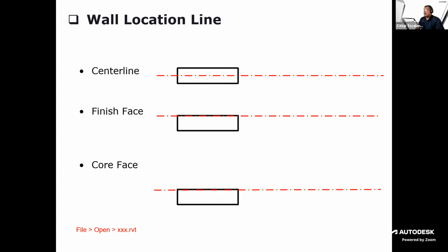For example, if you have a building that has a constrained site, and you want to make sure that the wall type does not overlap the property line, then maybe the envelope walls are aligned to the finish face from the schematic phase. So as you are defining this, in Revit,